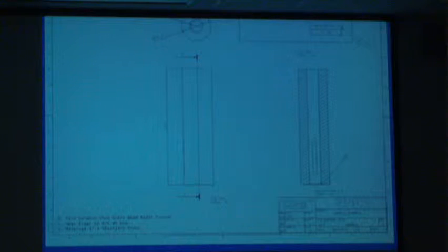My slides shifted off a bit. The next thing you'll notice is you've got a base view, which is way up here at the top, and then two projection views. So one to the side and one below it. So a base view, you'll pick one way that you're looking at the part, and then the projection, you'll rotate the part down and to the side. And if you have a more complex part, you may have more projections, okay? So that's a pretty typical layout.